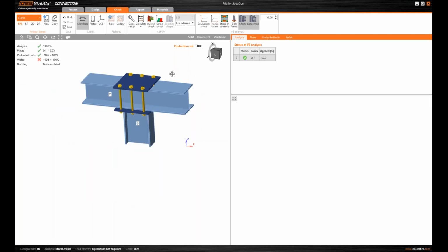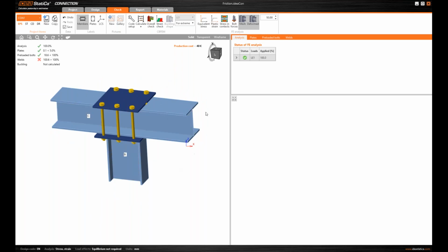So this is the correct way where we can use this, even when there is no friction in the numerical model between the plates, right? The contact works in pressure only. So that's a conclusion of the tip. This is quite often a question on our help desk,